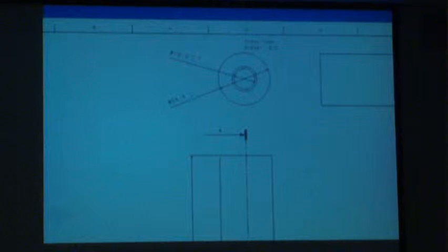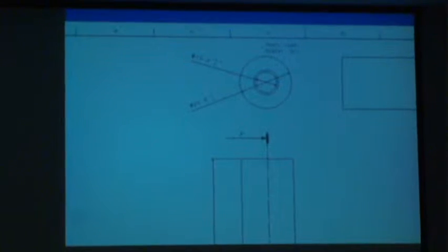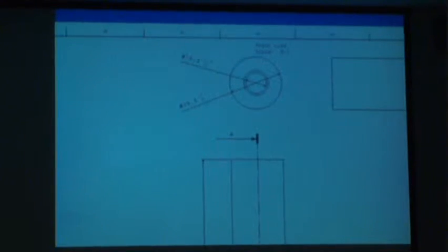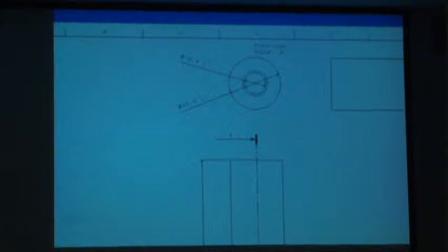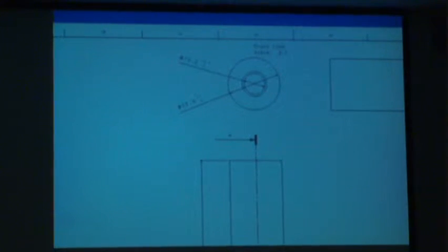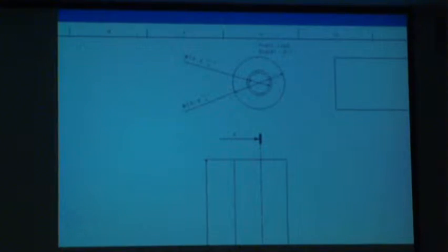That means I would accept any diameter between 26.5 millimeters and 25.5 millimeters. Okay? And there's a lot of reasons why you would specify things in different ways, but that's the basic format. So anytime you look at a print, and you don't know what all these numbers are, that's just telling you the range that you will accept. Because as long as you have a fine enough measurement tool, you can never make a perfect part. So if it's supposed to be 25.5 millimeters, you will never get 25.0000000 forever. There's no perfect manufacturing process. You have to state some tolerance band.